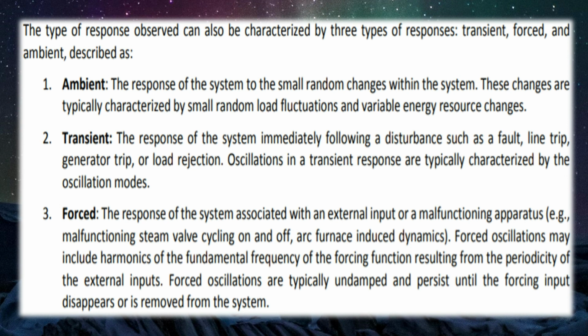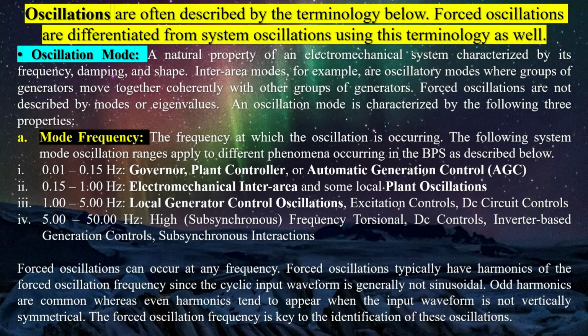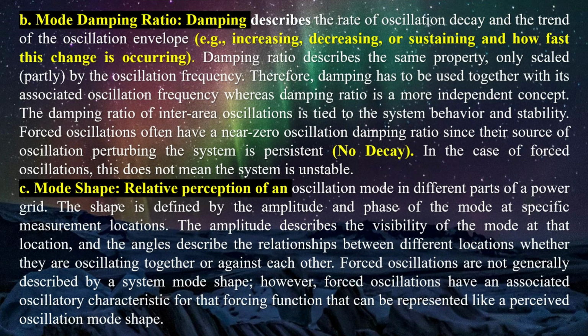Forced oscillations occur when an external periodic input, such as an oscillating steam valve in a turbine generator, causes a power swing or any other reason. These oscillations have been known for years, but they have become more visible recently due to the installation of phasor measurement units (PMUs). The explicit formulation of the oscillation is formulated in terms of forced disturbances and system mode shapes. The forced oscillation amplitude, components, and envelope are intensively studied. Consequently, measures for mitigating the oscillation are obtained.